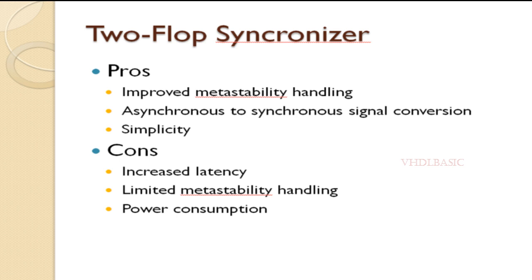It's important to note that the choice of synchronizer design depends on the specific requirements and constraints of your system. Other synchronizer architectures, such as synchronizers with a higher number of flip-flops or Gray code based synchronizers, may offer different trade-offs in terms of latency, metastability handling and power consumption.